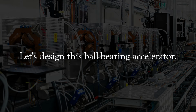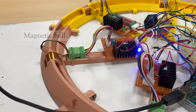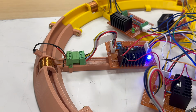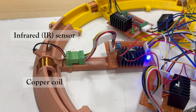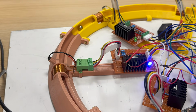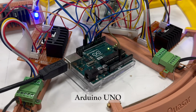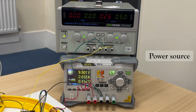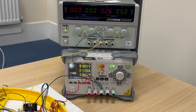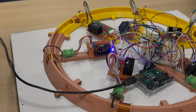Now let's design this ball-bearing accelerator. To accelerate our magnetic steel ball on the circular track, we use an IR sensor and a copper solenoid coil to synchronize the ball's arrival time with the accelerating field. This process is controlled using an Arduino UNO microcontroller board. The setup needs two DC power sources, one to power the IR sensor circuit and the other to supply the voltage and current to generate the magnetic field.